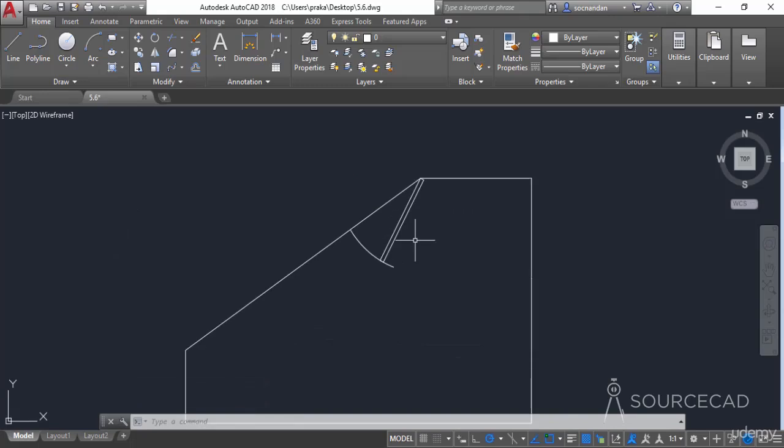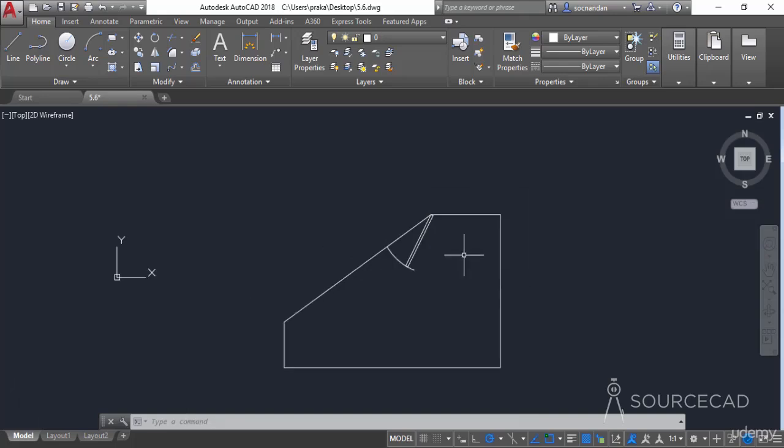Now in this case, you can clearly see that the first point is here where we clicked. The second point was the midpoint, and obviously I said that by clicking the midpoint, we are essentially assigning this line as the second point. So here the second point has been assigned, and the third point decided the direction, whether inside or outside. And here we have it, the object not only moved but also properly aligned according to the geometry. And using this tool, you can also align similar kind of geometries on different objects. So that was the align tool of AutoCAD.